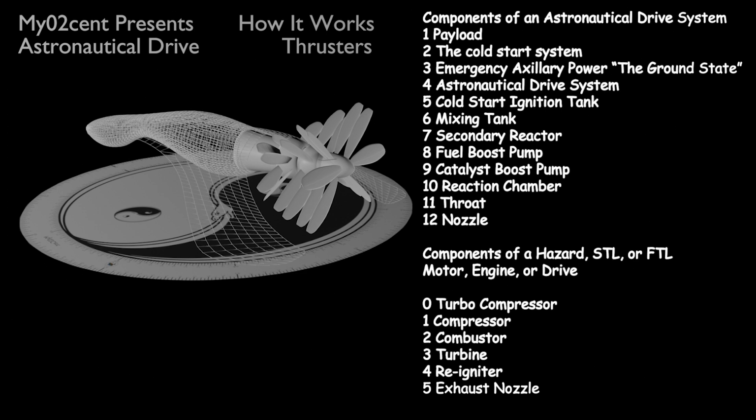3. Turbine. Third is the turbine. Like the compressor, the turbine consists of blades. As the high pressure and high speed air escaping the combustor moves through the turbine, some of the energy from the air is exchanged with the turbine. As a result, the turbine rotates or spins. As the turbine is connected directly to the compressor, the compressor also spins more rapidly. Controlling the exhausted air coming from the combustor regulates directly the turbine and indirectly the compressor.